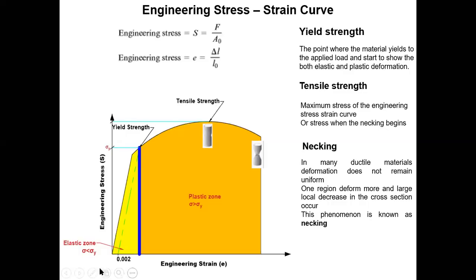Right? So now you keep on increasing the applied stress. When you apply the stress, then under these stress levels, it shows plastic deformations, right? So at this point, the material will start necking. That means it shows a visible reduction of cross section like this. I'm not sure if you can see this clearly.